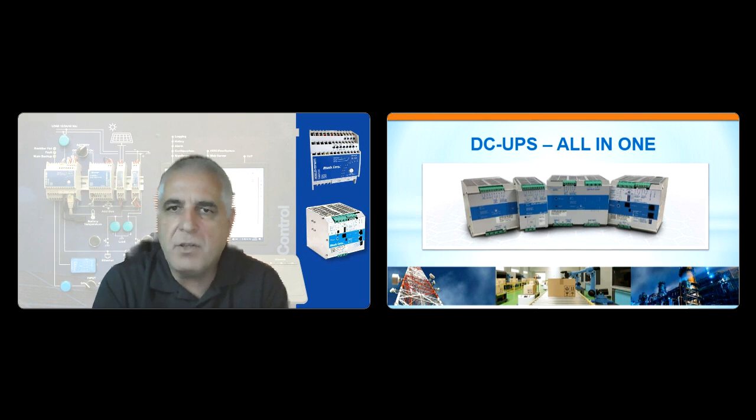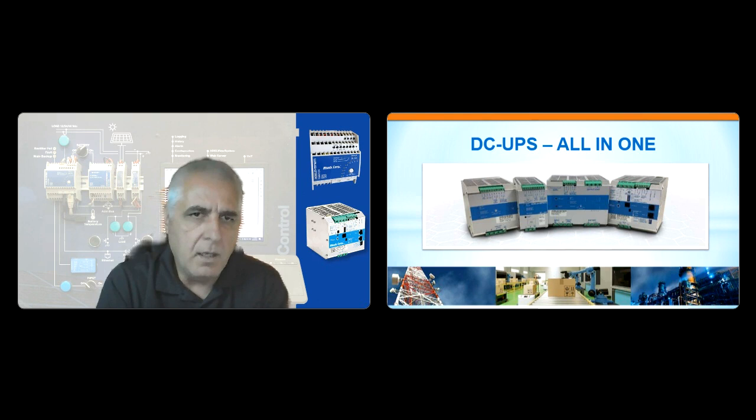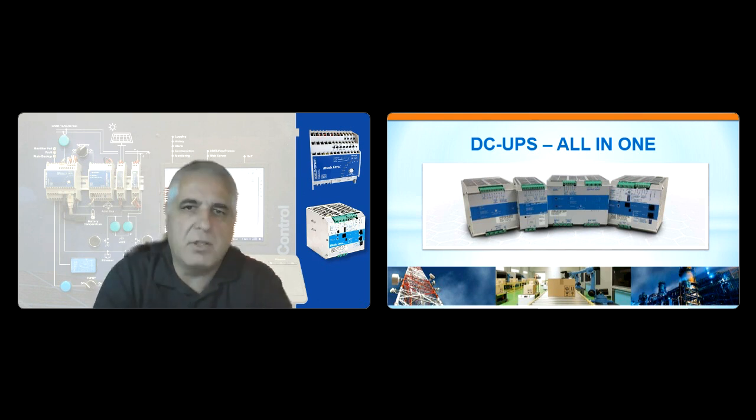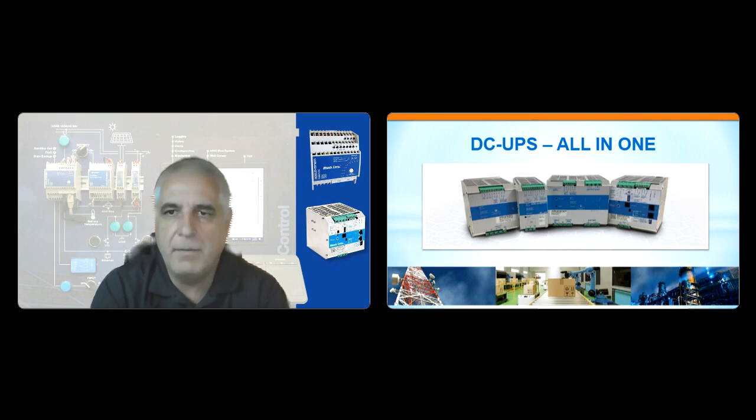They can also function as a power supply, particularly when designed into the UPS system. Other common applications for battery chargers include consumer and industrial electronics devices, barcode readers, and tablets. Battery chargers supply electrical energy to a rechargeable battery in a controlled manner, typically through a multi-stage process that incorporates a bulk charge, absorption charge, float charge, some even more.